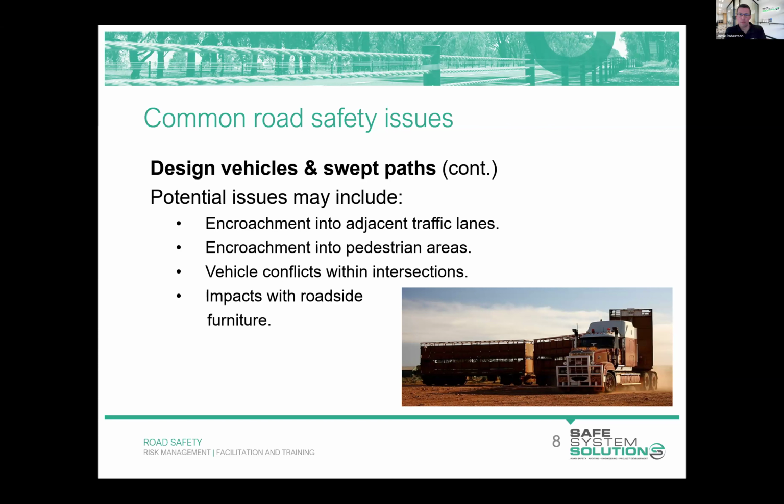In general, the longer the vehicle, the greater the swept path, but that's not always the case. Some long multi-combination trucks perform quite well. So it's not necessarily the longest vehicle that is critical in terms of space. I guess it's the worst performing vehicle as far as swept path that we are concerned about, but also the longest vehicle that can have implications for storage space and other things. So there might be multiple vehicles that you need to consider on some occasions.